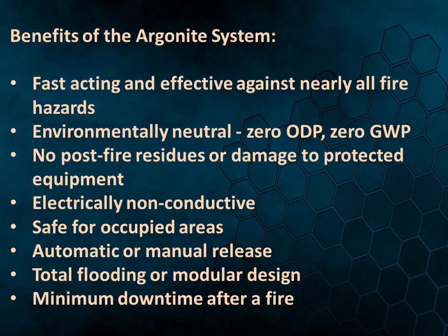Benefits of the Argonite system: fast-acting and effective against nearly all fire hazards. Environmentally neutral, 0 ODP, 0 GWP. No post-fire residues or damage to protected equipment. Electrically non-conductive. Safe for occupied areas. Automatic or manual release. Total flooding or modular design. Minimum downtime after a fire.